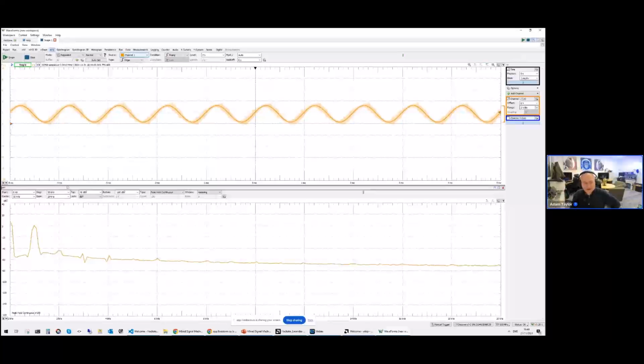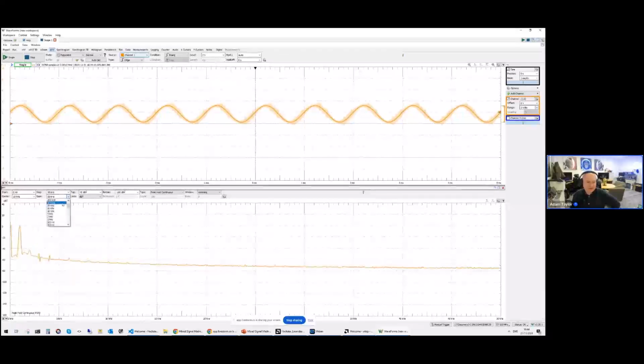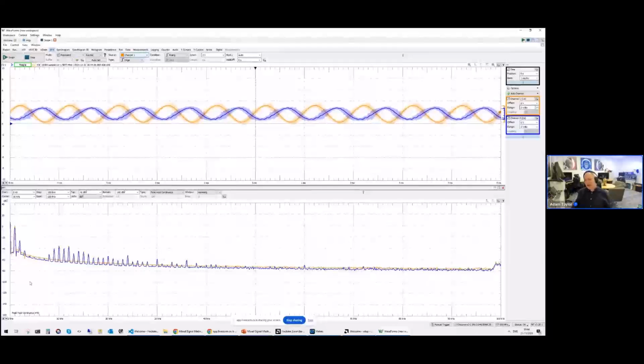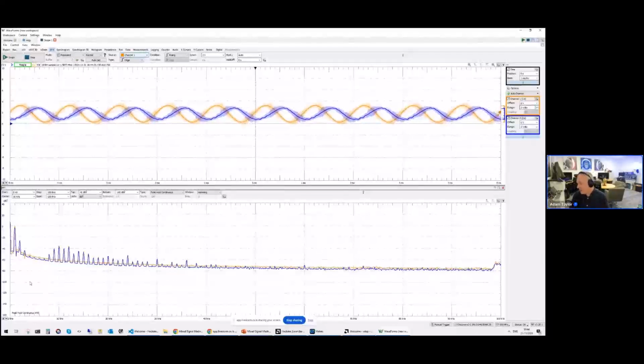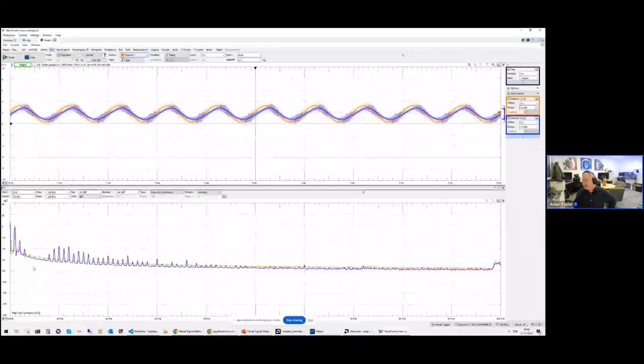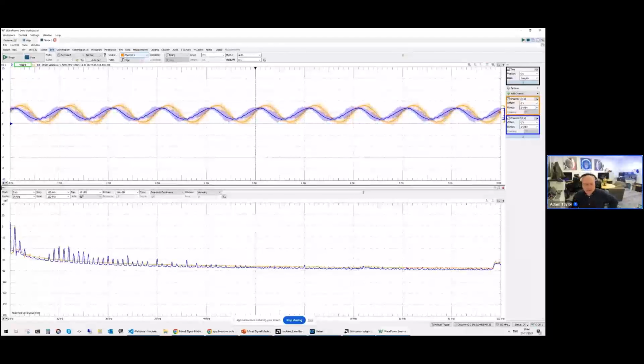And we also have a lot smoother spectrum coming out the back end of this. So we've got our 1 kilohertz tone here. And if we extend this out, say if we go to 50 or even to 100, we can see that we don't really have, unlike with the PWM, if we turn channel 2 on, you can see just how bad it is. Unlike with the PWM, where we have a lot of harmonics coming through it, and we'd need a lot more filtering. With the delta sigma, we get a lot nicer, smoother output, which works really nicely.